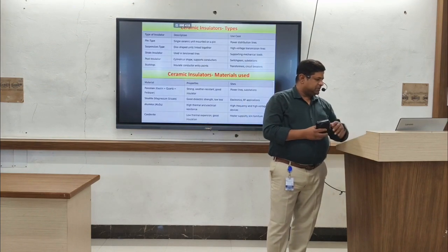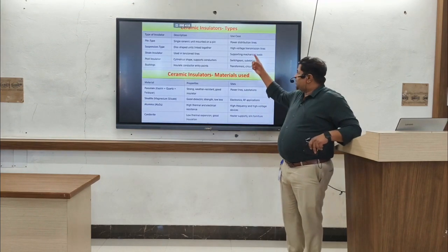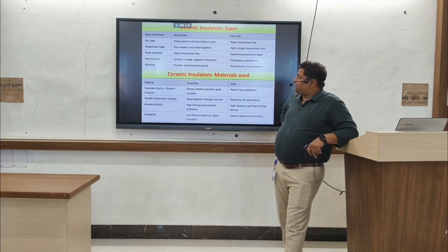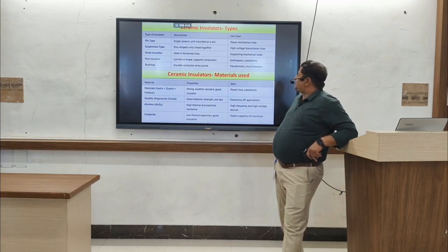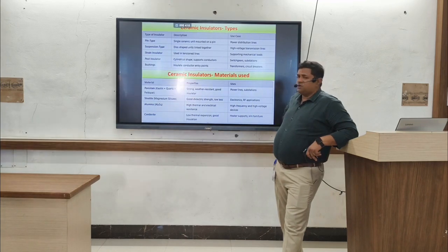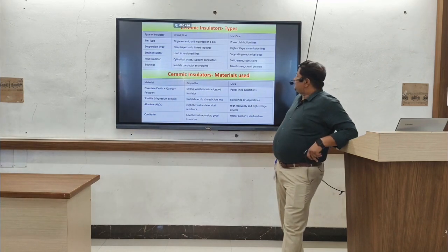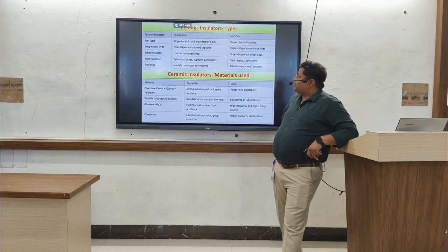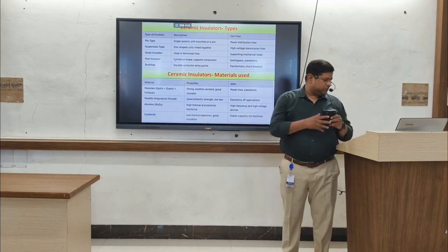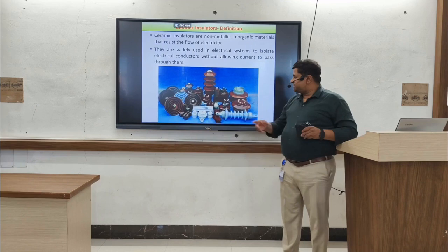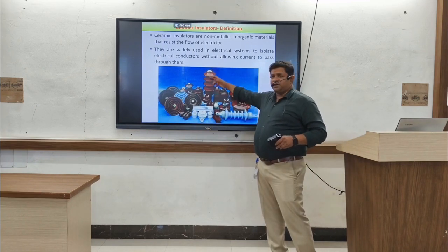There are some types. I have taken the tables here. Some ceramic insulator types are pin type, suspension type, strain insulator, post insulator, and bushings. Their description and use case are also given. Pin type is a single ceramic unit mounted on a pin, and it is used for power distribution lines. Suspension type is a disc-shaped unit linked together. It is used in high voltage transmission lines. I am talking about these shapes. Here we have seen this kind of disc shape.